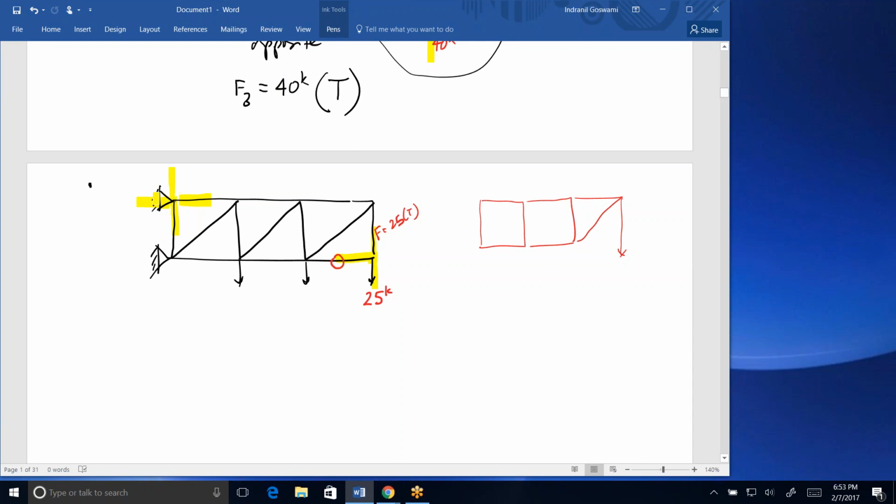The four forces altogether are all organized in two lines of action. So whatever this member force is, this horizontal one, will be equal and opposite to whatever the member reaction, or the structure reaction, is here, horizontal. And same thing for this other pair. But because they're in pairs, I can't say that either one is a zero force member, right? So I can only say that they occur in pairs.